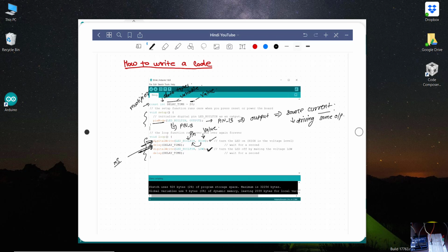So in this case, LED was high, then it waited for 20 milliseconds, then again it was set to low, and then again similarly in this line LED is waiting for 20 milliseconds, and after this the program control again goes back to the first line, that is the digitalWrite LED_BUILTIN HIGH, and it will keep running this piece of the code.